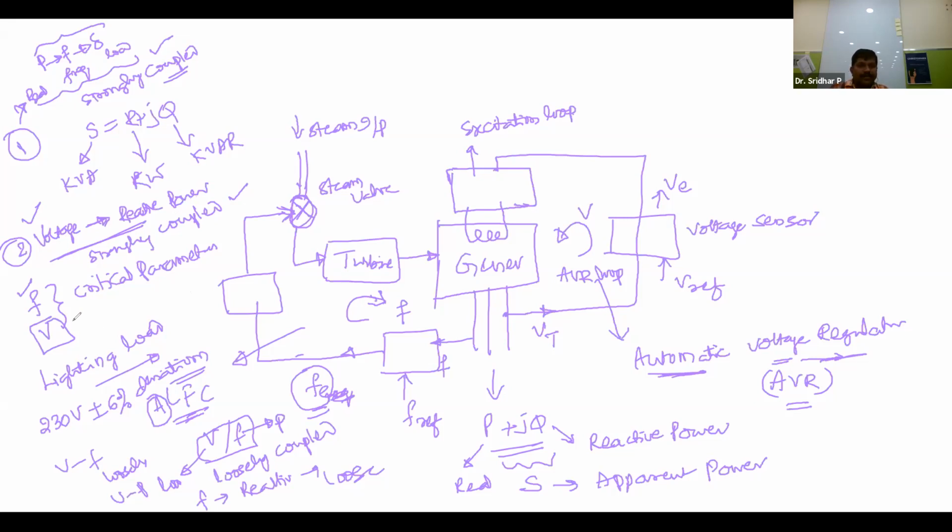So here, what is the role? Why voltage is to be maintained constant means voltage it will be maintained. You can maintain voltage as a constant by maintaining reactive power as constant. Now, why, how? What are the real power and reactive power? Real power is P equals V into I into cos phi. Reactive power is represented as Q equals V into I into sin phi.